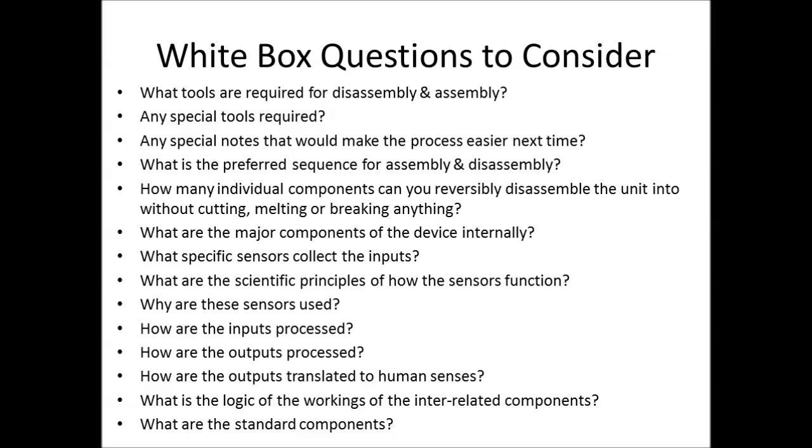So here are some of the white box questions that you want to consider. What tools are required for disassembly and assembly? Any special tools required, power tools, anything that might be more difficult to acquire for this? Any special notes that would make the process easier the next time? What is the preferred sequence for assembly and disassembly? And you can show that with pictures. How many individual components can you reversibly disassemble the unit into without cutting, melting, or breaking anything?